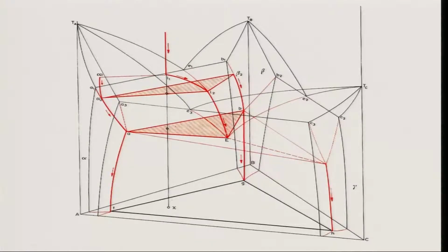In all these cases, what will happen? The first thing it will do is crystallize both alpha plus beta. Suppose I take an alloy composition corresponding to this curve E1E. As the alloy is cooled down, it will hit this surface. So, this will crystallize both alpha and beta, finally it will reach L2, from L2 it will move to capital E, where it will crystallize alpha plus beta plus gamma, correct.